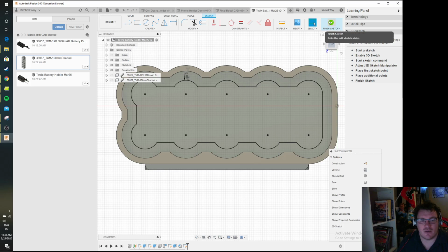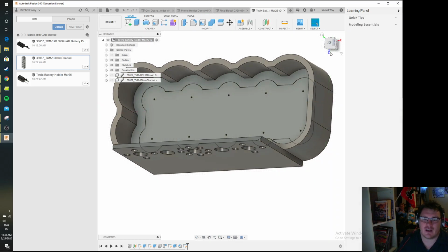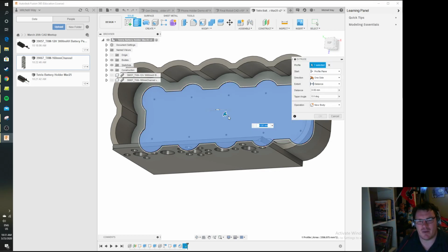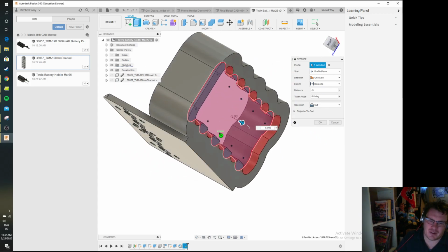This sketch is going to give us something to cut out. If we ever have to save weight, which again, FTC doesn't happen nearly as often, I'm just going to go distance -5 millimeters, because I know that this piece is 5 millimeters thick.